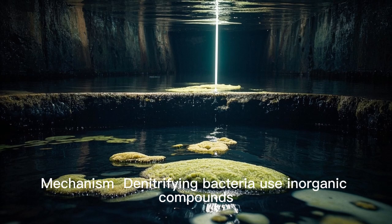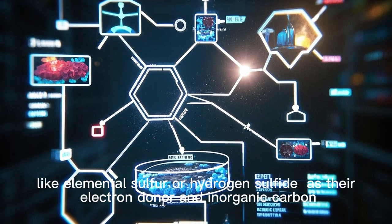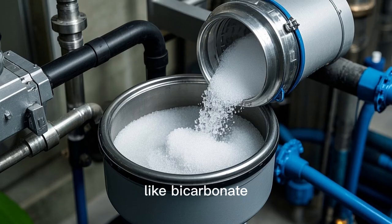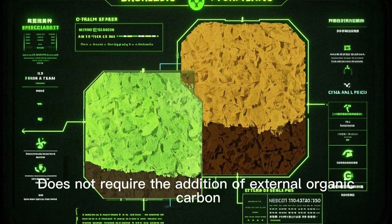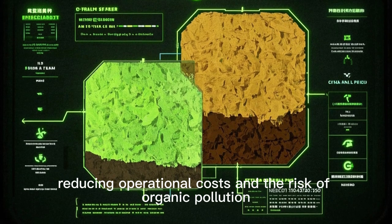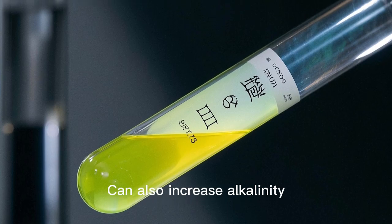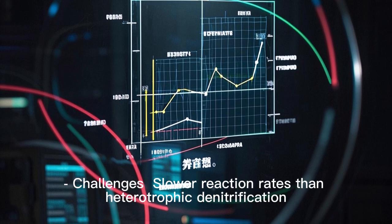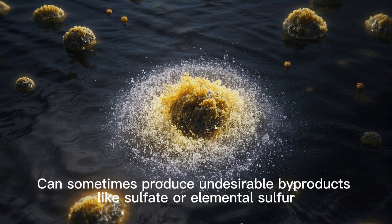Autotrophic denitrification. Mechanism: denitrifying bacteria use inorganic compounds, like elemental sulfur or hydrogen sulfide, as their electron donor and inorganic carbon, like bicarbonate, as their carbon source. Advantages: does not require the addition of external organic carbon, reducing operational costs and the risk of organic pollution. Can also increase alkalinity. Challenges: slower reaction rates than heterotrophic denitrification. Can sometimes produce undesirable byproducts like sulfate or elemental sulfur.